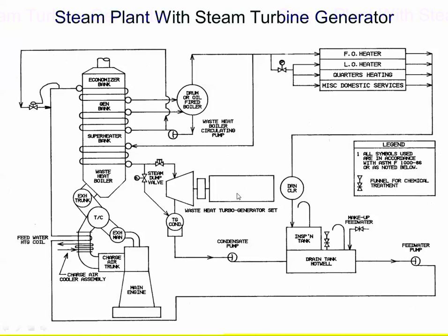So let's take our simulator. In our simulator, we have a shaft generator on the main engine, and we have a steam turbine. It's a fairly modern, very efficient engine. I have a limited amount of waste heat available that I can use for producing electricity. It's not enough for the whole plant. So you're going to have the shaft generator on and this on at the same time.